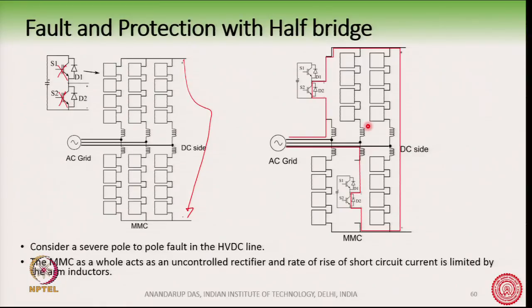But anyway, what I want to say here is that the rate of rise of the current will be limited by the arm inductors, and that is how we should choose the inductance, so that under worst condition also the current is limited.